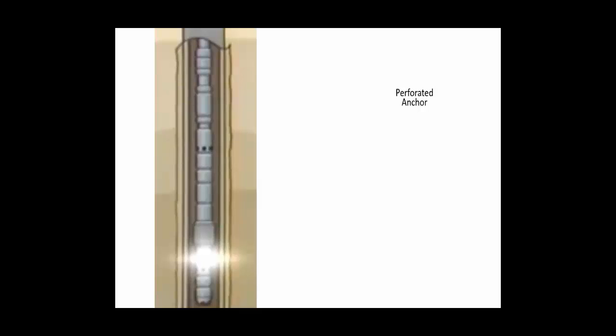In the simplest form, the drill stem test tools run on either drill pipe or tubing, consist of flow control valves, a fluid sample chamber, an inside pressure recorder, one or more packers to isolate the zone being tested, a perforated anchor for flow to enter the tool string, a temperature recorder, and a pressure recorder.